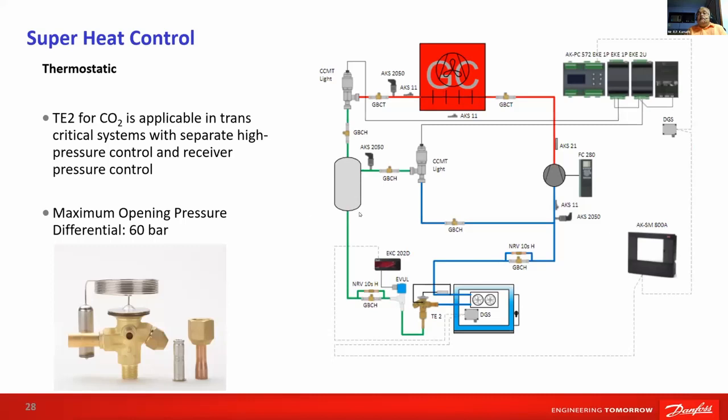One big difference in this is that the pressure incoming to the expansion valve is always intermediate pressure, not high pressure. Let us say I have a very simple system with no separator or intermediate pressure, and I'm just feeding directly from the gas cooler. That's not possible, as you may pass vapor also. It may be supercritical, a high pressure gas. I will not say it will not work, but it is not the way it would be recommended.